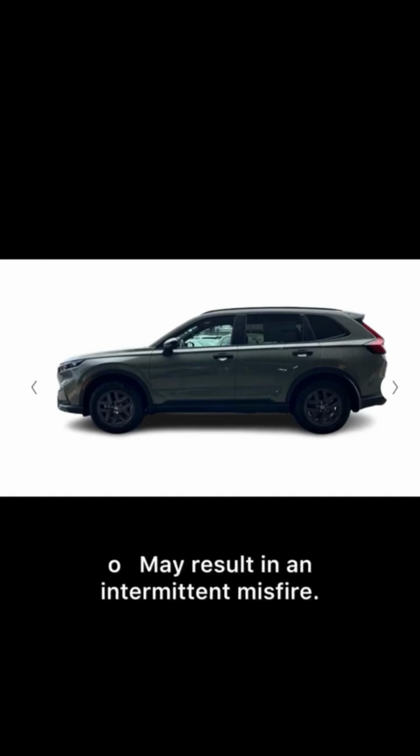To provide a path for exhaust to safely leave the engine. Mufflers cool exhaust, reduce exhaust pressure, and reduce exhaust noise. Resonators reduce exhaust noise. Catalytic converters reduce harmful exhaust emissions. 2. What is the purpose of the oxygen sensor in the exhaust system?